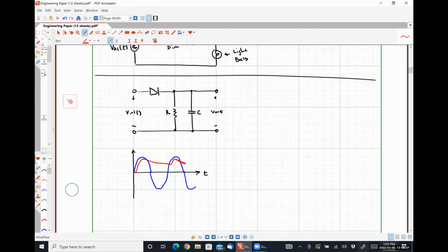And as our input voltage increases, we are going to see that our capacitor begins to charge, and we should see a peak value of the voltage drop across our capacitor of exactly V in minus V D on, using our constant voltage drop model, right? Well, once our capacitor has a voltage of V in minus V D on, and then our input voltage begins to decrease, what happens to the diode?